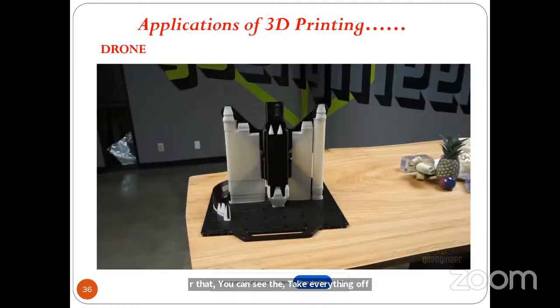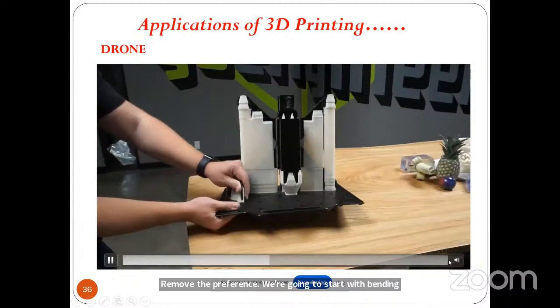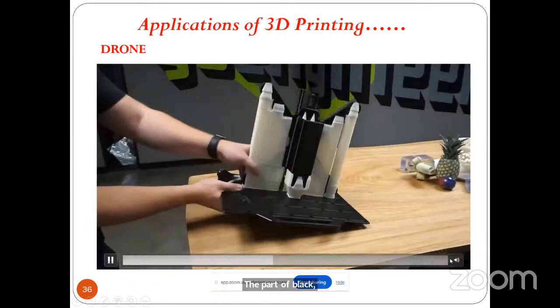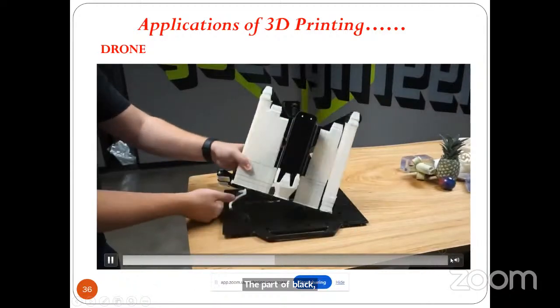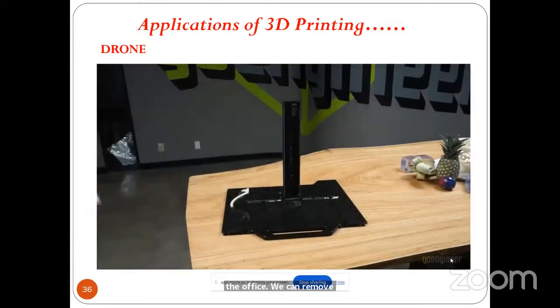To remove the prints, we're going to start with bending the build plate and then peeling the print from it. The bottom black color is the builder plate. We're going to do this for both the prints. And then once we've done this, we're going to take it over to the ultrasonic bath, and the white color support structures are dissolved off. We can remove these support structures.